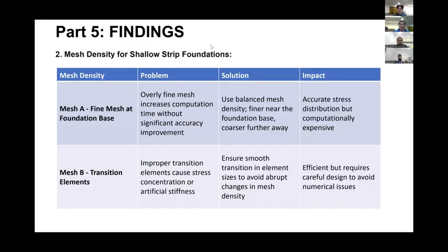The second topic is about the mesh density for shallow strip foundations. We have two types of mesh. Mesh A is a fine mesh at the foundation base. The problem is that an already fine mesh increases the computation time without significant accuracy improvement. Our solution is to use a balanced mesh density, finer near the foundation base and coarser far away from it. The impact is an accurate stress distribution, but